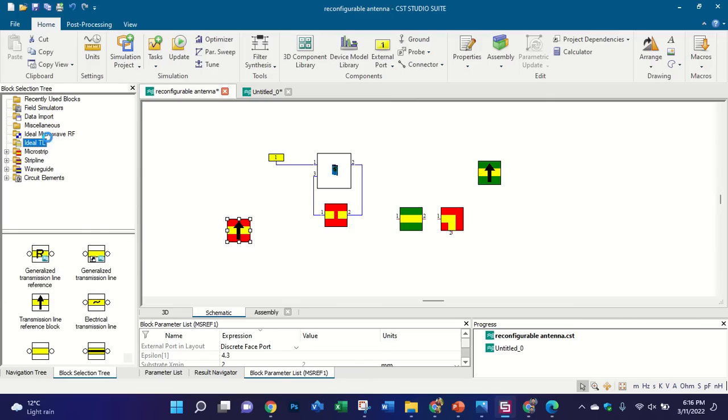No, this is the name of the file, like you have for the S2P file. I know, yes, I know this SPICE. My mind went in another direction. I guess we can import all this schematic diagram into SPICE, because I know it can be opened by the SPICE which we use for electronics. Yes, for electronics, you cannot even directly import the ADS file in this schematic option. So you need to export as a SPICE file from ADS, and then you are able to import it in this schematic. I got it.